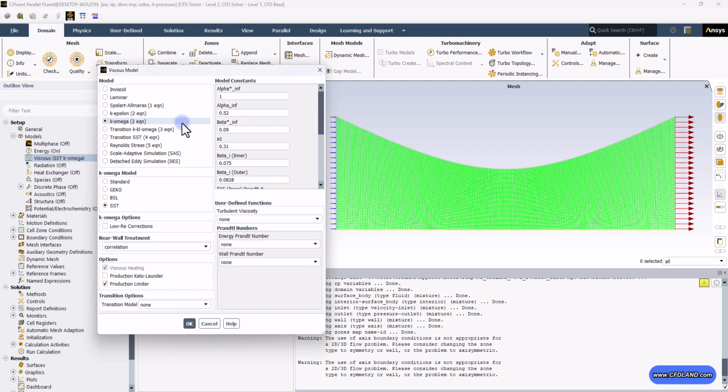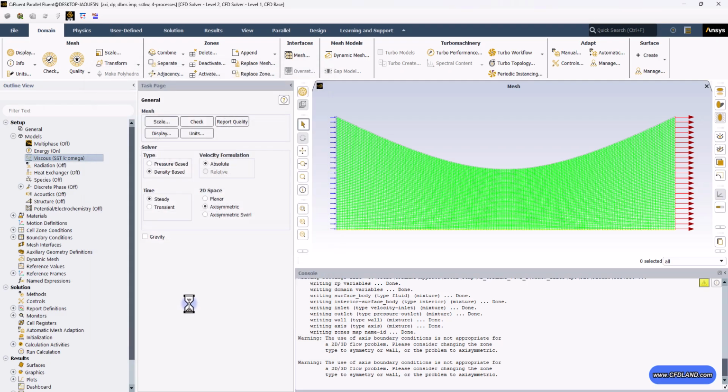Although ANSYS Fluent provides different turbulence models, our choice here would be the k-omega SST turbulence model. So this is the best model for aerodynamics. It is very smart. It acts like one model in the free stream far from the walls of the nozzle and a different model near the walls. This makes it perfect for nozzles where the air friction against the wall is very important. And all in all, we can conclude the SST k-omega model is the best one when it comes to this.